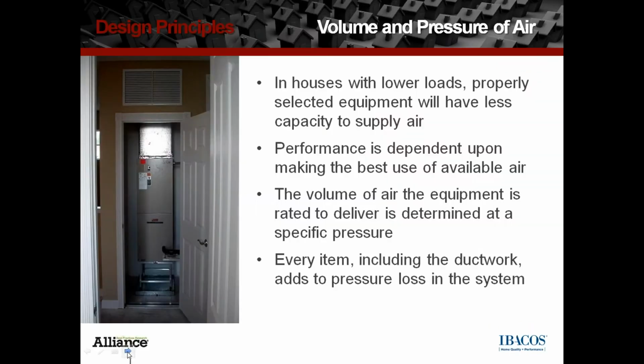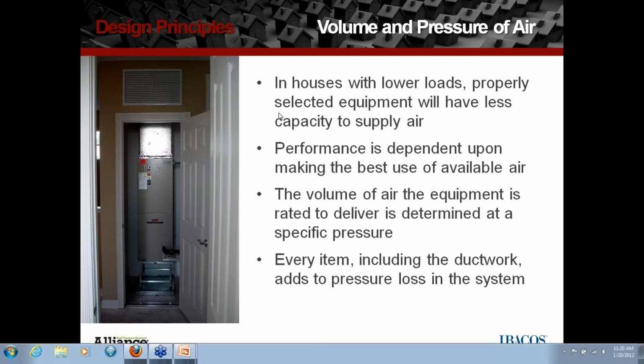Design principles. Again, kind of repeating what we said earlier, but the house with a lower load is going to have less air required to condition it, so smaller equipment is required. The performance of the system is really based on making the best use of that available air, and that's what we're going to talk about in our supply delivery strategies and our return strategies, is getting the most use out of that air.